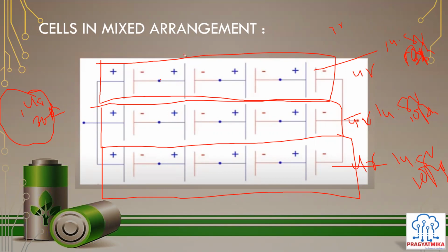So using the BMS, we can only measure the voltage across the terminals of the cell. If it is a series-oriented connection, based on that we make all the decisions, like how much balancing would be done, or how much capacity is left that is effective, for the NMC cell I'm talking about. If it is LFP, then the total current also gets considered.